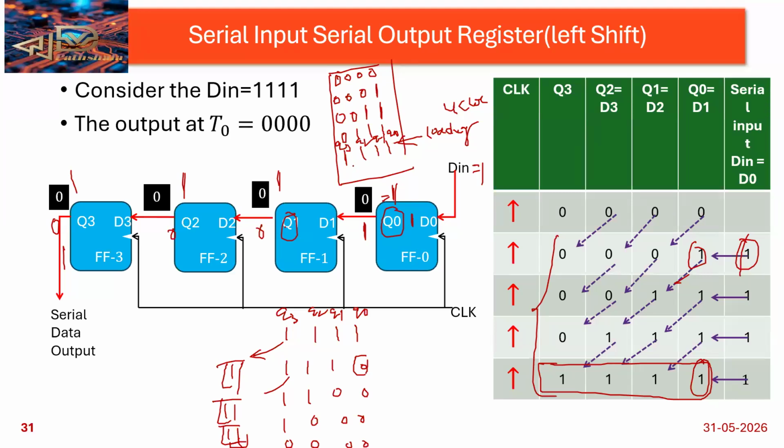But in this shift register, again I want to store the data. That is not possible, since it is not 0 here; the data is still loaded. I want to empty this. For emptying purposes, how many clock cycles are required? Four clock cycles. All these bits are moving to the right side, coming out, and 0 will be stored because I'm not giving any data. It will take 4 clock cycles because 4 bits are there.